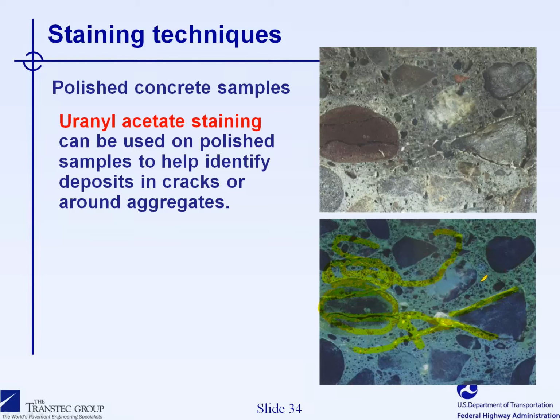So whether or not it's going to deleteriously affect the freeze-thaw performance of the concrete, possibly not to the extent of the cracking itself, because obviously when the water freezes and thaws in the cracks generated by ASR, this is going to be the main mechanism responsible for or contributing to deterioration.